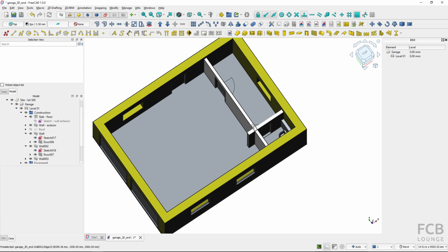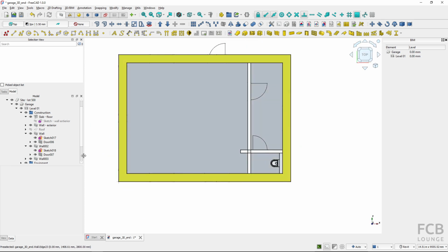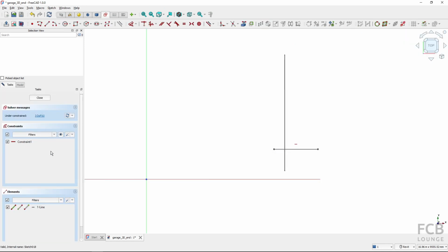And now if I want to edit these walls, I would use the add again sketch tool. So basically, if I wanted to make this wall up to here, I would double click this sketch. So I'm editing this sketch, not this. This is external geometry. Working with the external geometry, it would make much more sense to join these two sketches